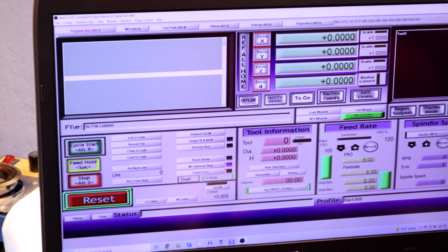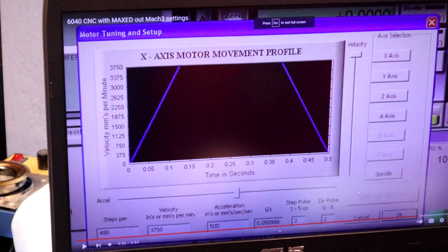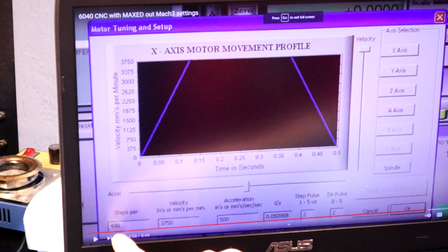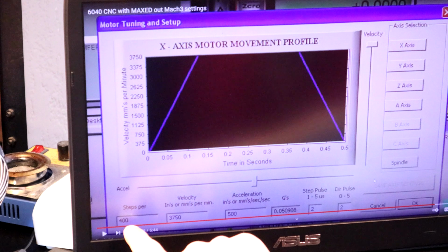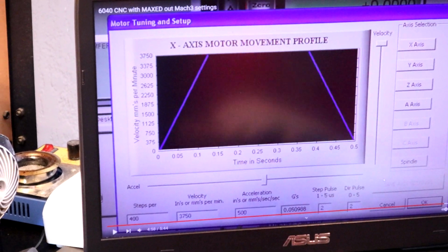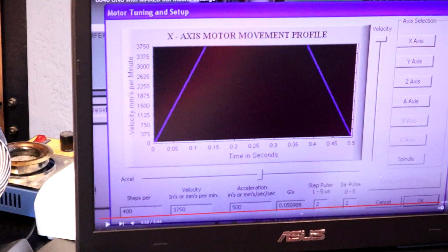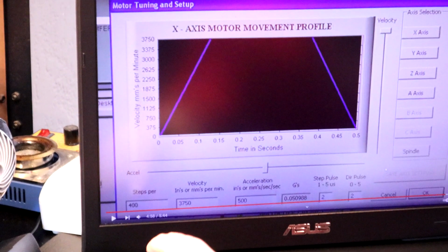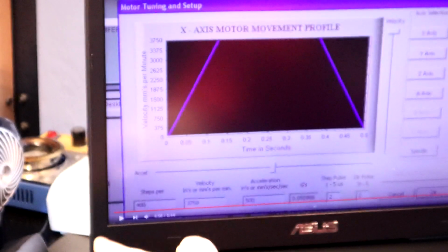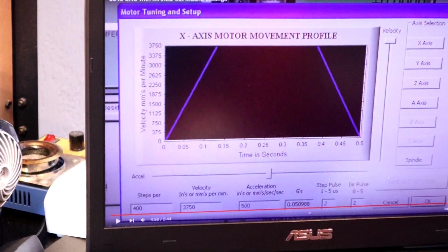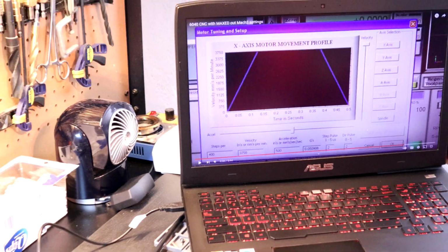Okay. First thing I want to cover is Rick's settings in the new video. The steps in Mach, steps per inch in his measurement matrix, is set to 400. Now, for those of you that don't understand how this works, very simple. We've got steps per inch. That means 400 he has set to equal 1 inch. That simply means that it only takes very minimal rotation of the shaft of this motor to equal 1 inch.